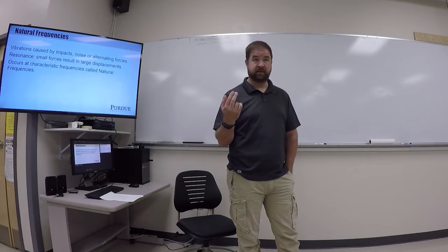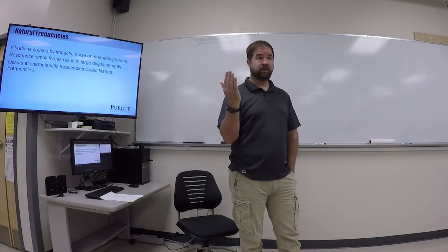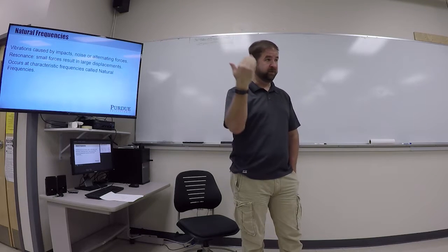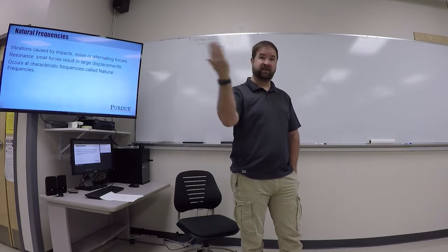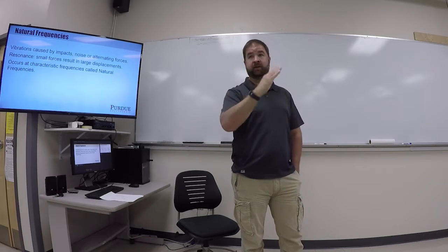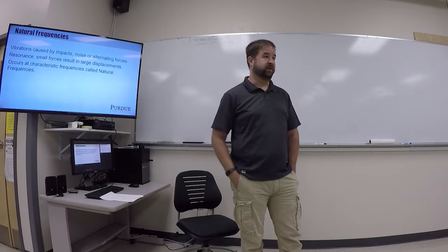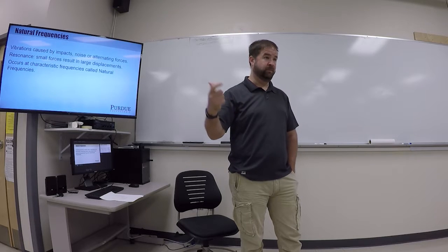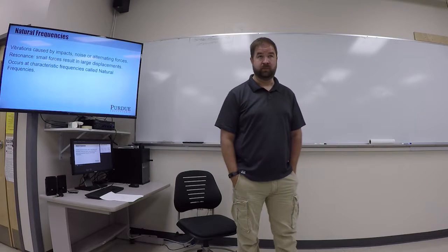And the article was saying that when the wind is blowing and the building is swaying, the elevator cables match the frequency of the building sway. And when that happens, then the cables start whipping back and forth in the elevator shaft, and it actually can oscillate enough that they start hitting the walls. And clearly that's not a desirable characteristic. And so we have to limit the length of the cable to not match a natural frequency of the building, which will cause them to whip.